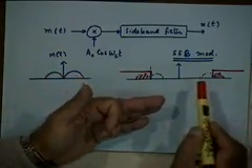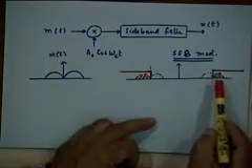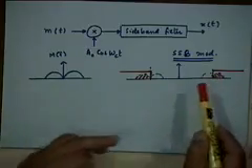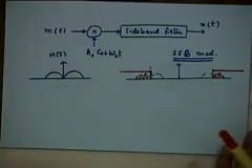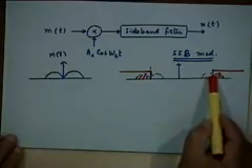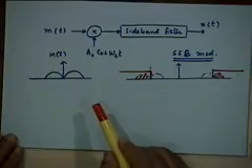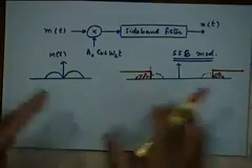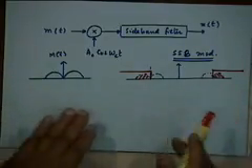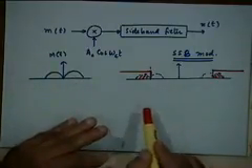In practice, we don't use low pass filters of such large bandwidth 0 to fc or such high pass filters, because in any case the signal has a finite small bandwidth, right? So it's more convenient to use band pass filters, either of this kind or of this kind, right? That will be the actual, but for theoretical discussion here, it is preferable to think in terms of high pass and low pass filters, as we will soon see.